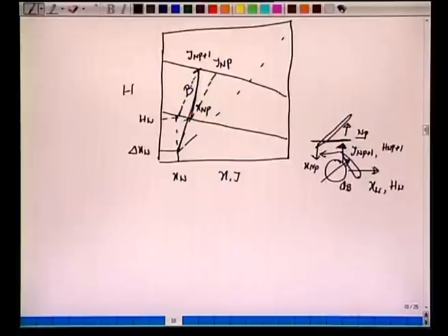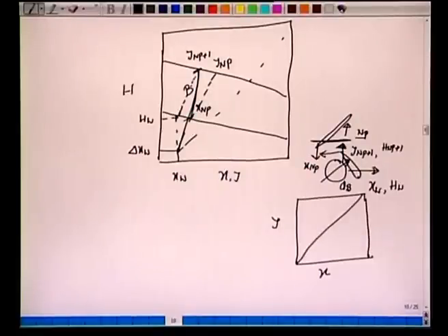Okay, and how do we get these two mole fractions? Again, one has to rely on the Y versus X diagram. So we have to make use of both equilibrium plots, Hxy as well as the Y versus X diagram. Every time we have to read Hxy, we have to come back, take this X, find Y, or take this Y and find X here. So for every liquid X Np mole fraction, we have to come back here, take the mole fraction, read, go like this.